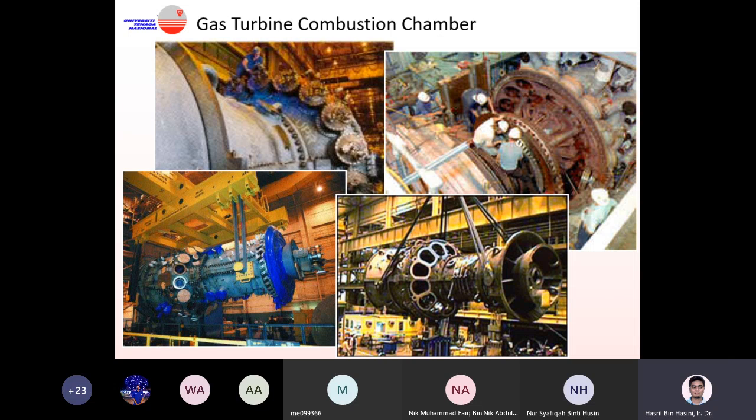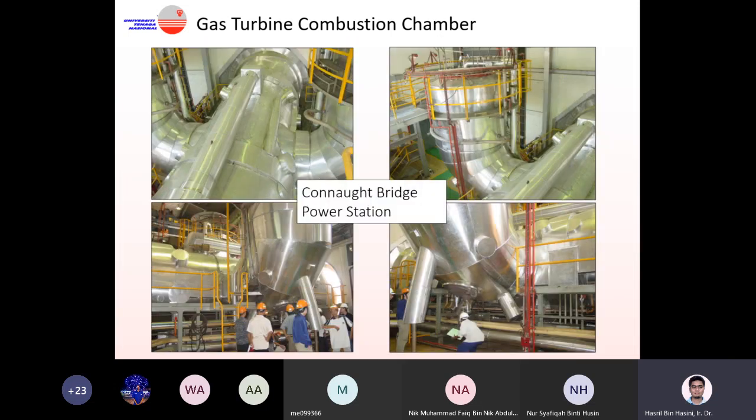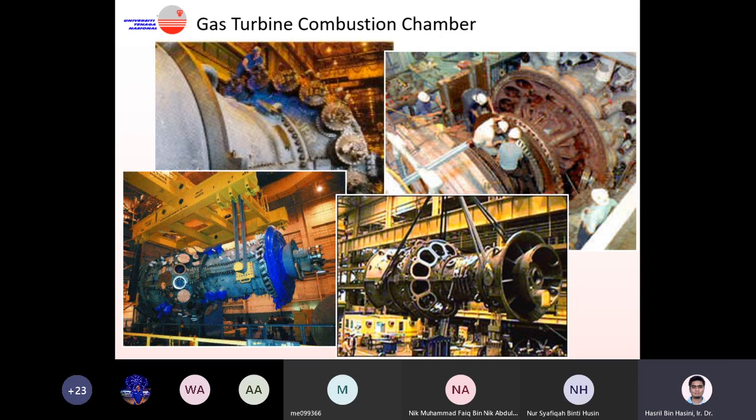So different types of combustor have different pros and cons, different advantages and maybe some disadvantages, especially with the big silo. When you have a big silo like this, you only have two combustors. If one is not working, you have the other one. But if both are not working, then your gas turbine cannot be used anymore. As compared to the can type, you can have many, so even if half of them are not working, you can still manage to keep the combustion going.